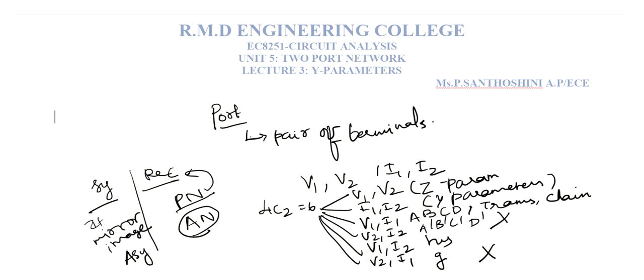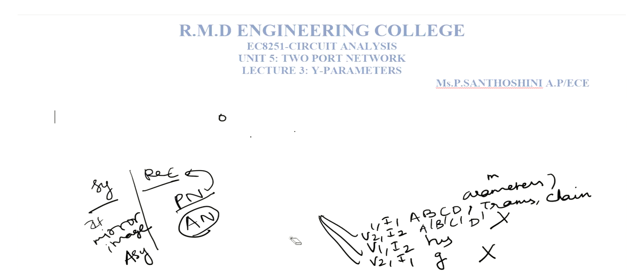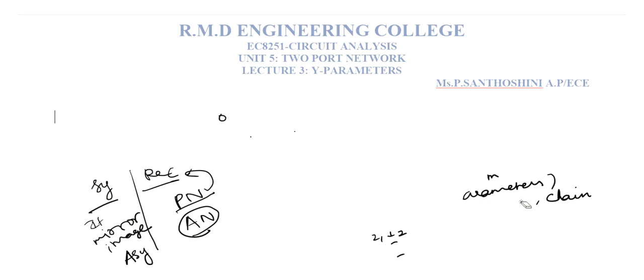The second lecture is about Z parameters. Z parameters are open circuit parameters. It is called open circuit because we make all the currents zero, I1 and I2 equal to zero. That's why it is called open circuit impedance. Z is always called impedance because in the AC domain the resistance is the Z parameter, a combination of R plus jXL. So in the second lecture we saw an overview of the Z parameters.